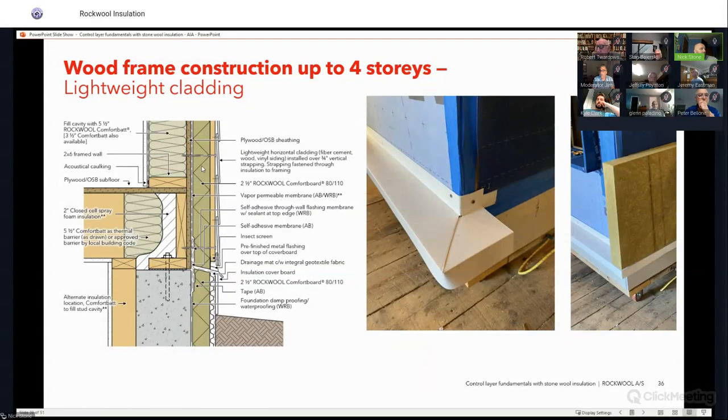From transitioning from above grade to below grade, like in here, having that nice control of insulation to here and also down to here. Typically, as you transition from above grade to below grade, you're going to have some type of water kick out system here. Water is a positively charged molecule, so as that water rolls down the wall assembly like this, it wants to wrap in down here at that sill plate and suck underneath. By having this kick out here, it's going to force that bulk water away from that building, which is going to save that sill down here at this location.